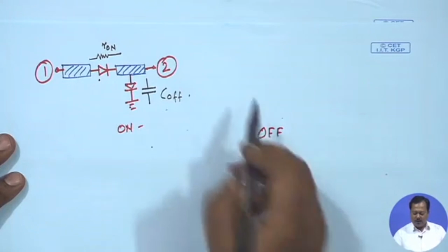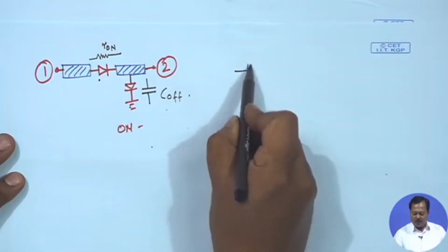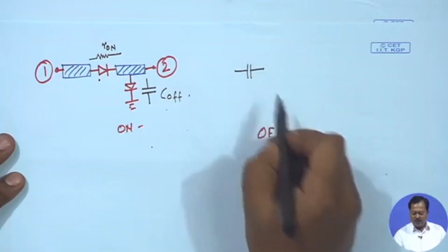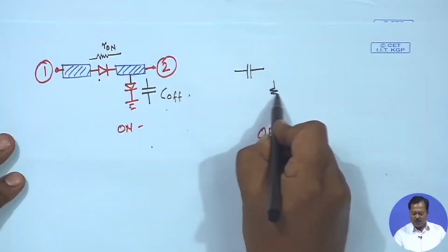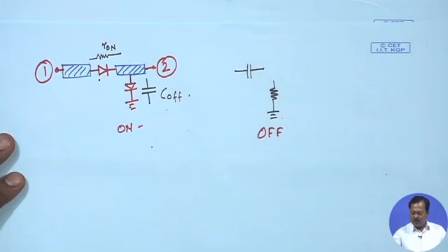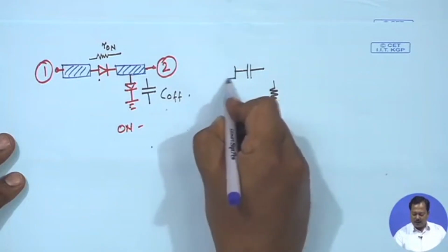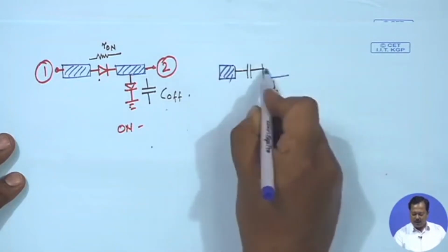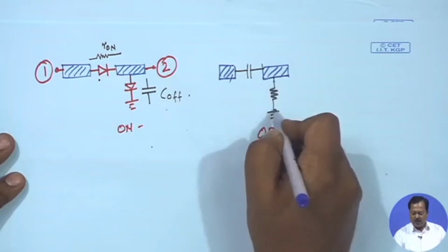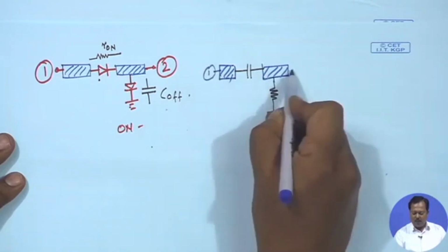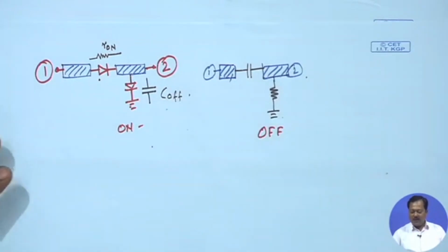Then in off state, this is just opposite. In off state, the first diode should be in reverse biased condition, and the second diode should be in forward biased condition. So, we have isolation due to the first diode and further isolation from the second diode. That is how we can improve isolation here, but insertion loss will degrade. But anyway, for any practical applications, we mainly look at the difference between the insertion loss and isolation.